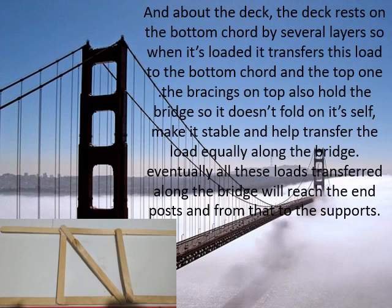And let me tell you something about the deck of the bridge. The deck rests on the bottom chord by several layers, so when it's loaded, it transfers this load to the bottom chord and the top one. The bracings on the top also hold the bridge so it doesn't fall on itself, and help transfer the load equally along the bridge. Eventually, all these loads are transferred along the bridge, reach the end posts, and from there go to the supports.